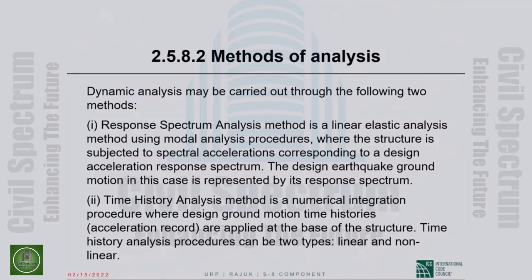Okay, dynamic analysis can be carried out through the following two methods. So there is modal response spectrum analysis and time history analysis, what is also called response history analysis. The modal response spectrum analysis is when a structure vibrates, let us say under earthquake ground motion. Remember, the foundation starts moving every which way all of a sudden in an earthquake. The remainder of the structure, because of inertia, cannot readily follow the movement of the foundation. It stays behind, and then tries to catch up with the movements of the foundation. That sets the rest of the structure in vibration.